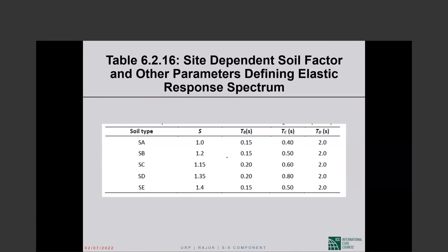Okay, this very important table in BNBC 6.2.16 gives you basically your ability to construct the design spectrum: site-dependent soil factor, and other parameters defining the elastic response spectrum.